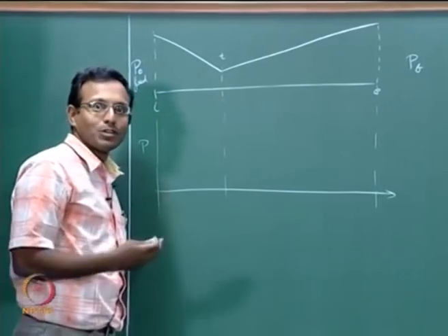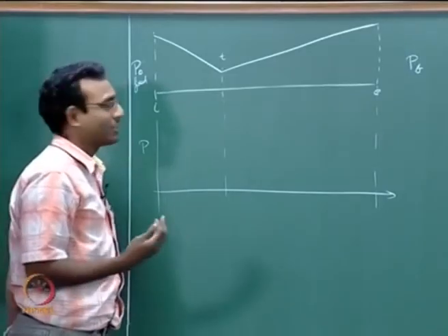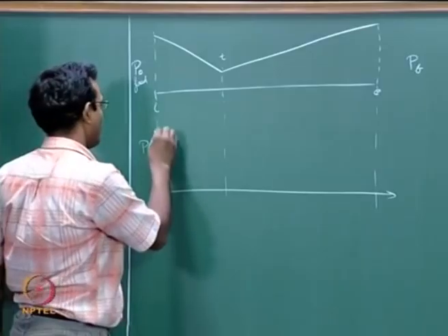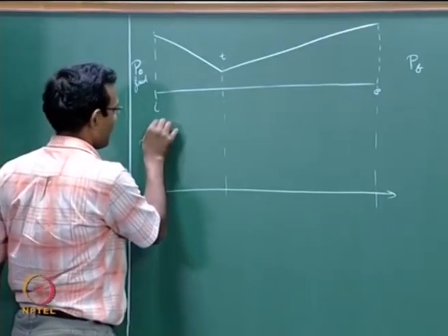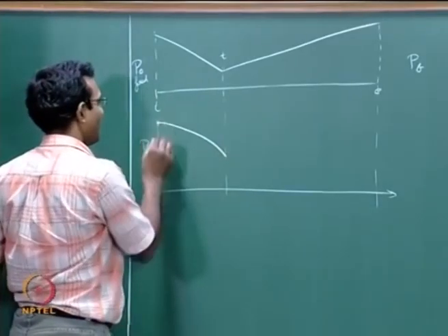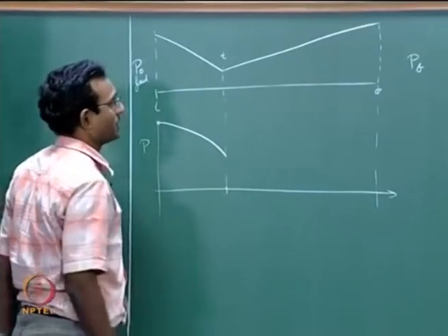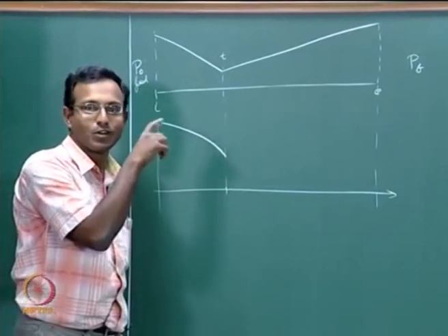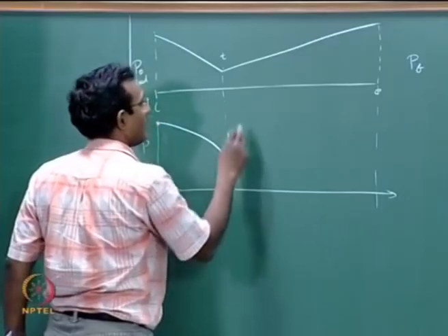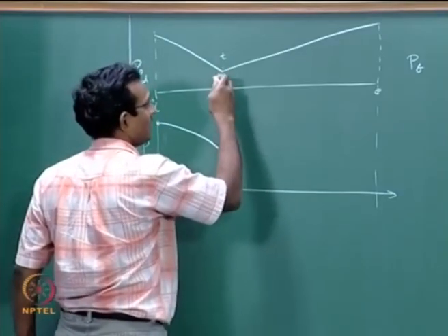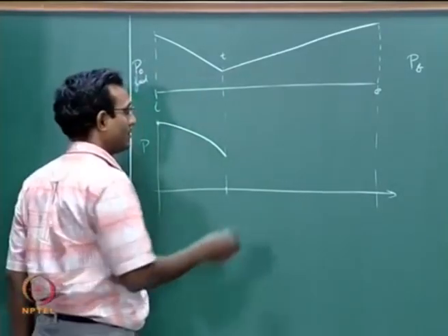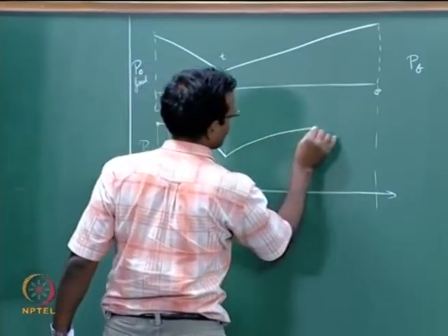But even if I think about compressible flows, when Mach number increases, pressure decreases, for isentropic flows, and we are still using isentropic flow. So I am going to get something like this, from inlet condition to the throat condition. I am calling it throat, I am not putting a star on top of it, only when I put a star it is choked condition. From here again I am having subsonic flow and it is a diverging duct, so my flow decelerates again and goes to some other value.